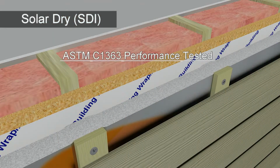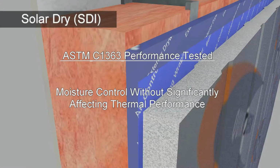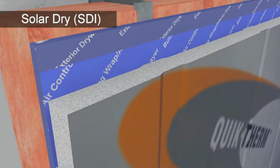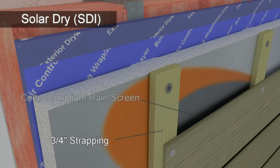Thermal wall assembly tests performed on Quik-Therm Solar Dry have shown that when installed as per manufacturer's instructions, the drying channels have a negligible effect on its effective R value. Thus, moisture control is achieved without sacrificing thermal performance. On the outboard side of the Solar Dry system are channels spaced either 16" or 24" on center. These channels accommodate 3/4" thick strapping, which create a 1/2" gap between Solar Dry and exterior cladding materials.